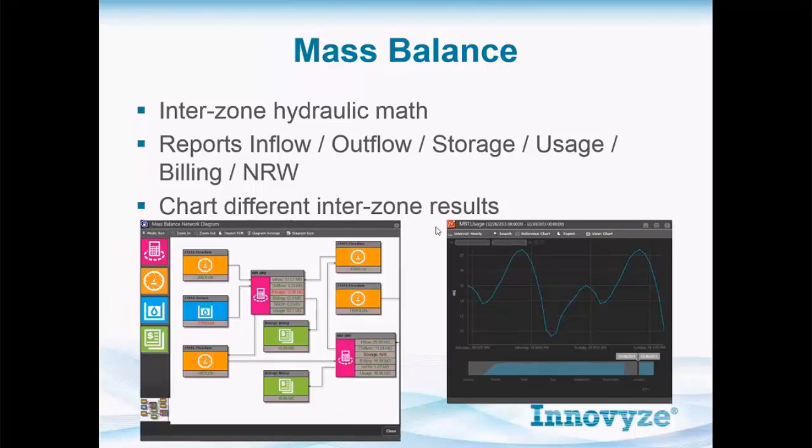Very, very easy to implement and edit and set up these different tracking and alarms. One of the most exciting things I think about SCADAWatch is the mass balance. This is a modeler's dream. Every pressure zone, here's a symbology here for a pressure zone. It's being fed by different flow meters, by tank level changes. So we're looking at each pressure zone individually, summing up the inflows, subtracting off the outflows from that pressure zone, and then adding or subtracting the change in volume from tank storage. So we're getting inflows, outflow, storage. We're also adding in billing records. So we're taking the usage and subtracting off the billing and automatically calculating non-revenue water for each pressure zone.